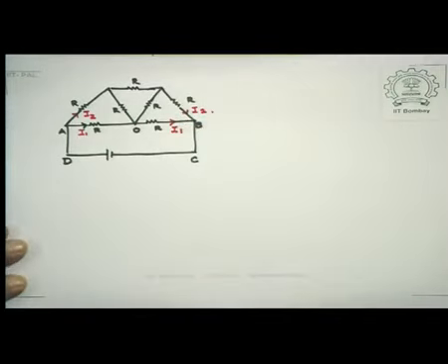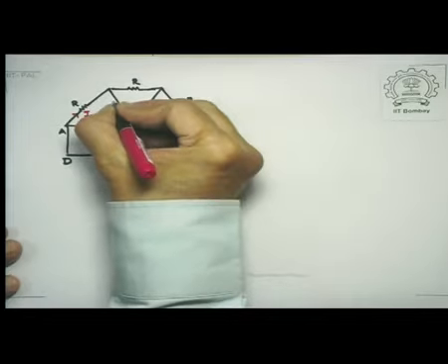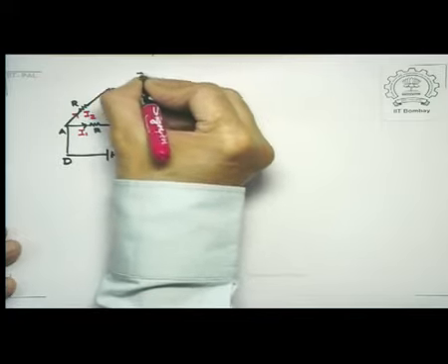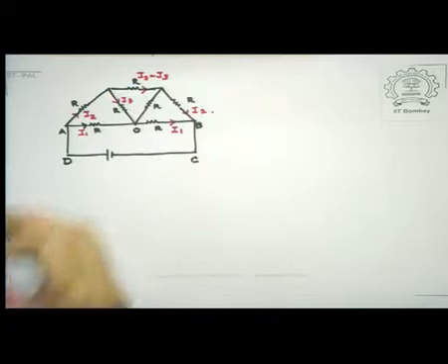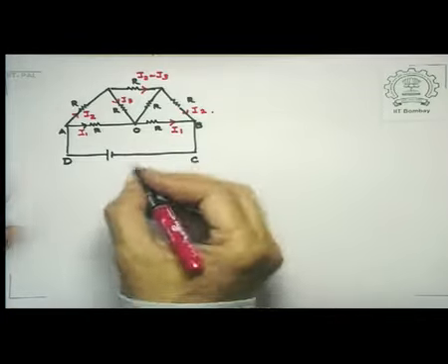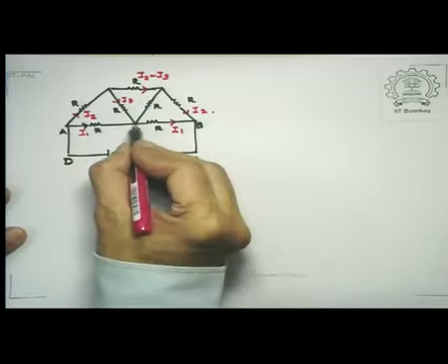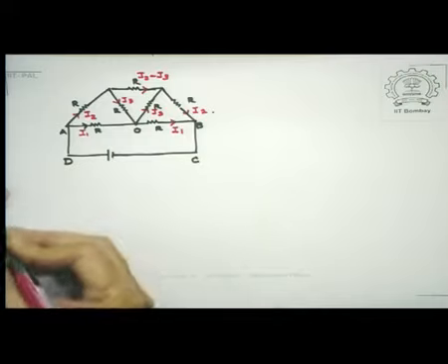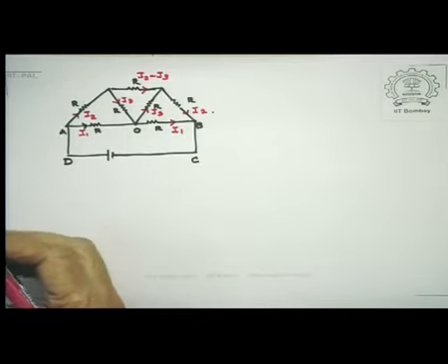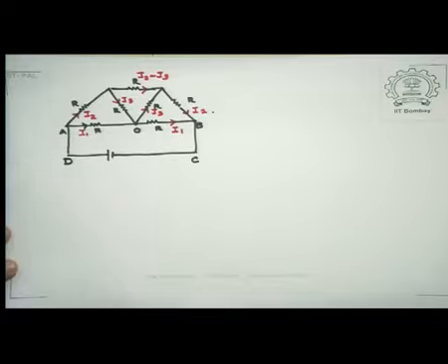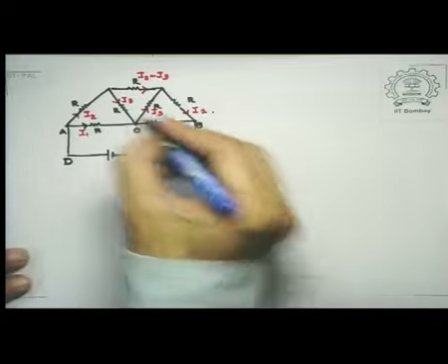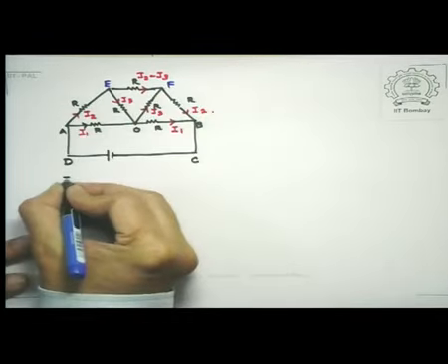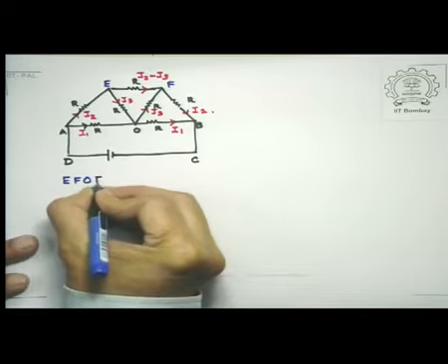So I can use the junction rule here now. Let me call this one as I3, so that this is I2 minus I3. And you can see here, since I1 is coming in, I1 is going out, so therefore this one must be I3, which was coming in from this branch. So let me now try to find out the relationship between them. Suppose I take this central loop. I already have used A, B, C, D. Let's call it EF. So let me take the EFOE branch loop.